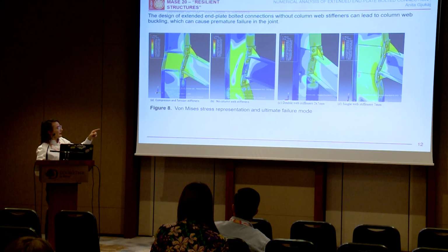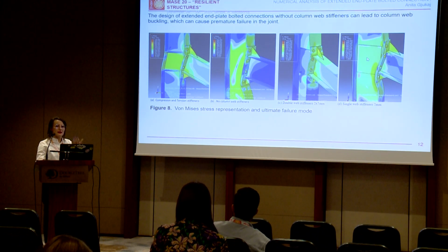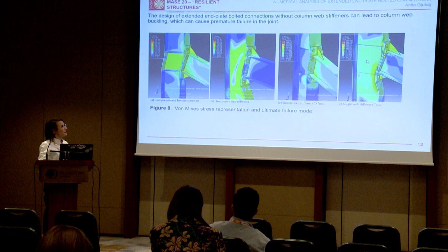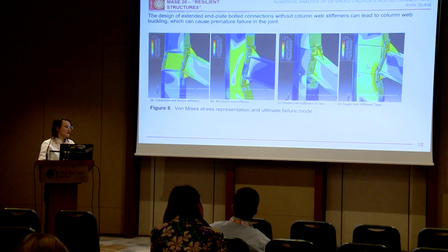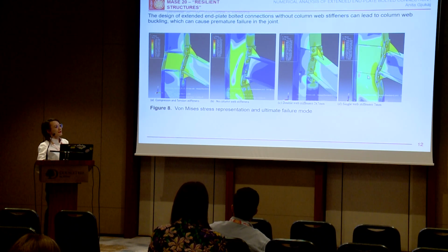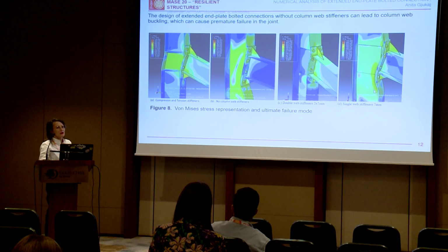While regarding the last one, applying a single web stiffener increases the cross section in shear, but not too much effect on the moment resistance of the joints. And the failure mode is due to compression buckling in the compression zone of this joint configuration.